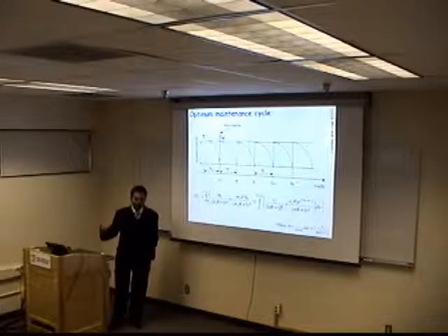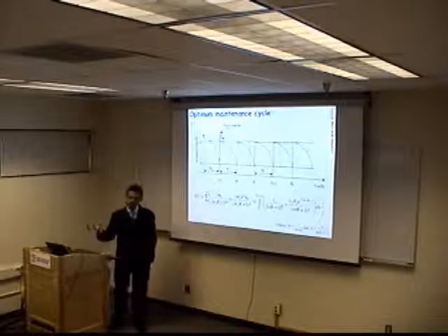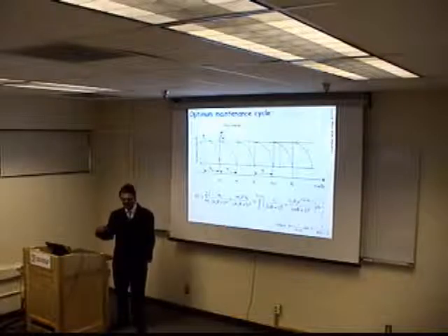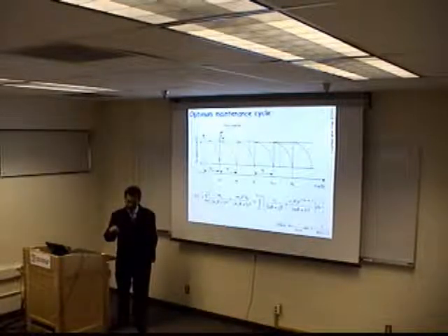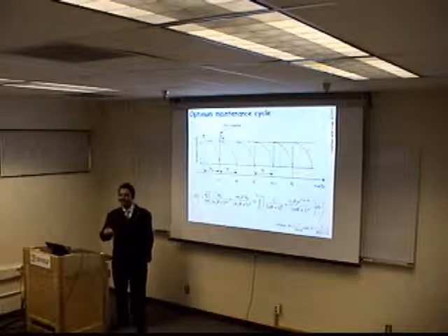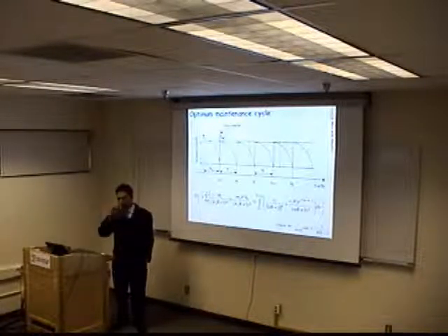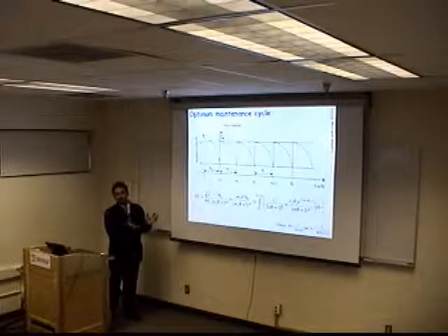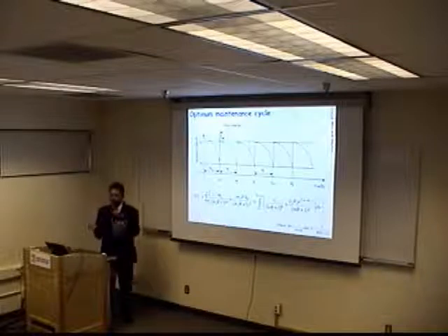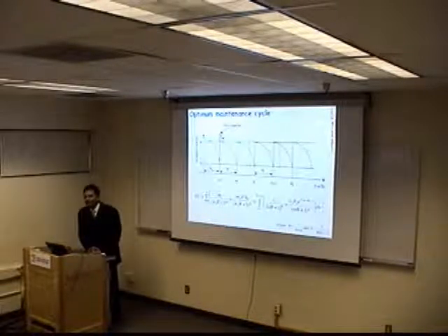Now one can of course upgrade it to different performance equations for different types of pavements and different traffic conditions. For example, for rutting, I am using the vertical strain on the subgrade, and one may disagree and say that strains at other levels and positions also have to be considered. But my presentation was more of a conceptual framework, and one can always add on to make it better and more rational.